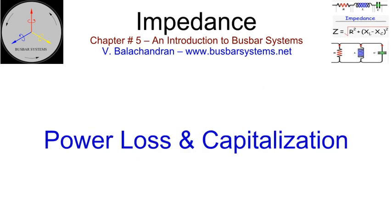Power loss and capitalization. One of the major constraints in the design of a busbar system is the maximum temperature a component can reach during normal operation. The limitation on the maximum temperature may be imposed by several factors, including but not limited to health and safety concerns, the capability of the insulation system, and the capability of the conductor to retain physical properties.